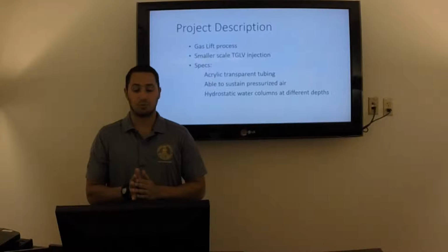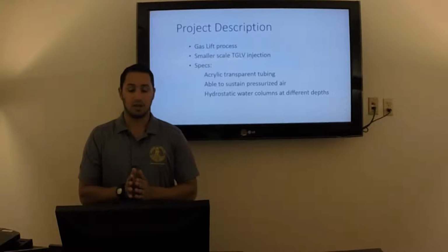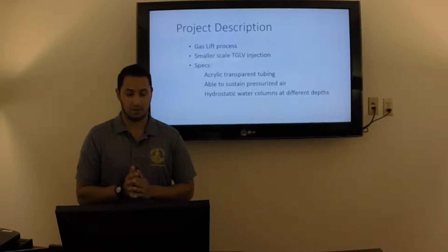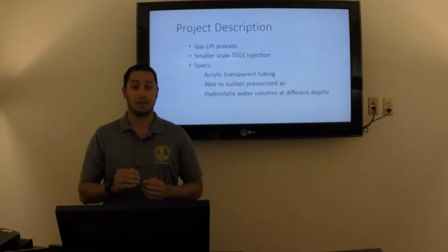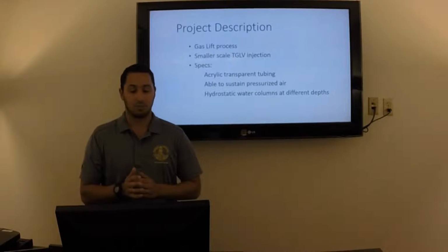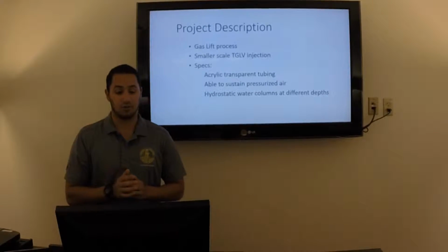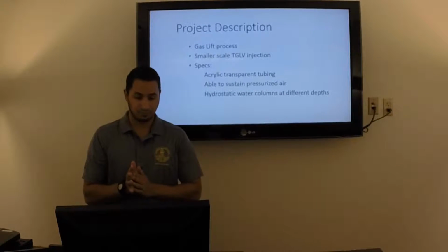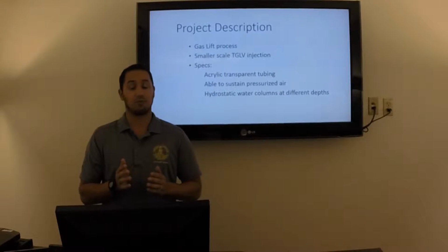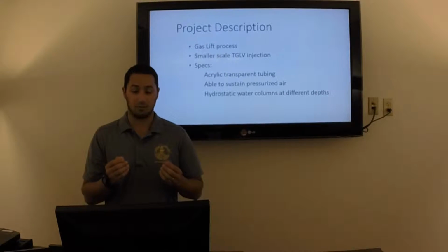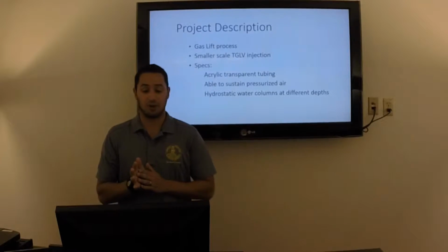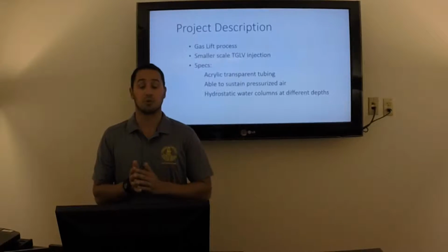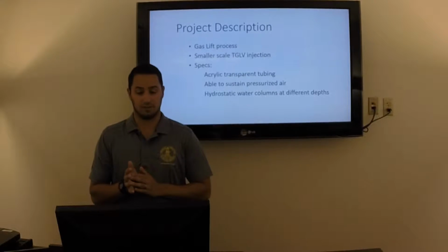As the gas enters the tubing string through the valve, it creates an aeration or bubbling effect in the liquid column. The gas bubbles expand as they rise to the surface, displacing the liquid around them and reducing the density and weight of the fluid within the tubing. This decreases the flowing fluid pressure, creating a differential pressure between the reservoir and the wellbore, and allowing the well to produce at its optimum rate.